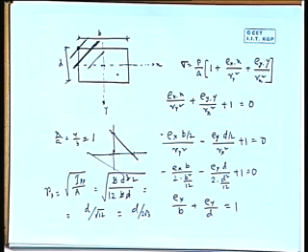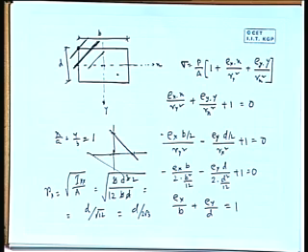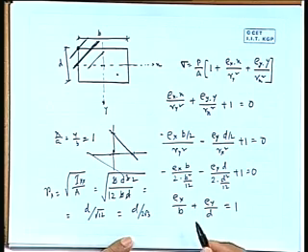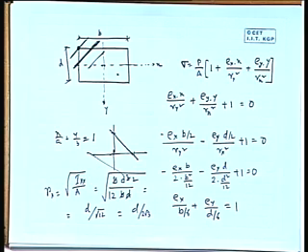Okay. Now, we want to get the limit of Ex and Ey. So, Ex and Ey, again it is giving a curve. Say Ex is a variable, Ey is a variable, it is x by a plus y by b is equal to 1, so we can get a line. No, that is the 6 part we have not taken here. So it will be b by 6 and d by 6. So, it will be Ex divided by b by 6, plus Ey divided by d by 6 is equal to 1.